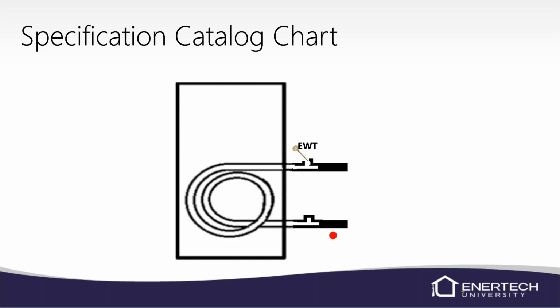Some of the other ones have a wider shaft, and once you try to pull it out of the PT port, sometimes the head comes off with all the wires, and then the shaft is stuck in that PT port. You've got to take a pair of channel locks and grab it out of there. I'd also recommend putting a little bit of water-based lubricant onto it, and it'll go into that PT port a lot easier.